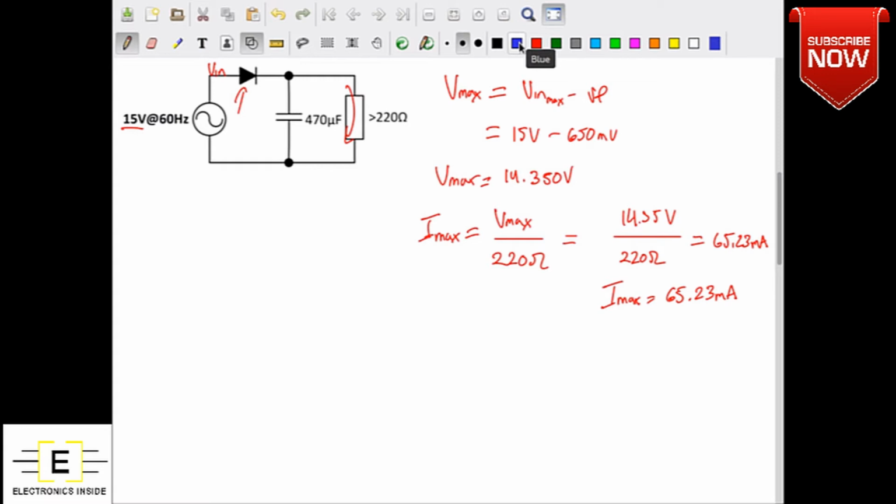And while it's not unreasonable to have to solve those kinds of equations when you want to be very precise, when you actually want to really get into a detailed description of the circuit, we're looking for a worst case estimate. So what we're actually going to do to make our lives easier is we're going to assume that the capacitor effectively charges instantaneously and thus spends the whole cycle discharging. And so again, because we're actually increasing our discharge time, we're increasing our worst case estimate. So we're losing a little bit of accuracy in our estimate, but we are, again, going to be pleasantly surprised when we actually go to our real circuit and find that it works a little bit better than our specifications.